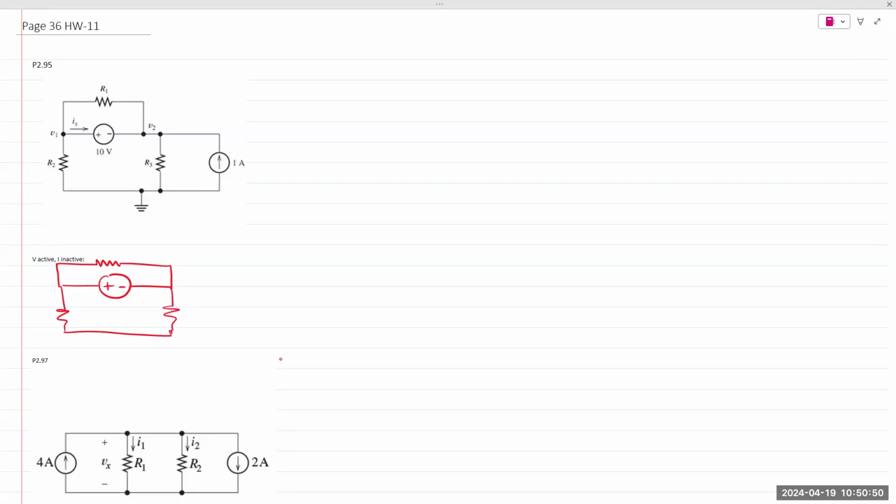And in the second one, you replace the voltage source with a short. Then you have a resistor, and then you have the current source. So again, these are the two circuits. If you look, the voltage source is now shorted out. That short, or the wire with 0 ohm resistance, is in parallel with R1. The reason I'm going over this is to explain that concept.